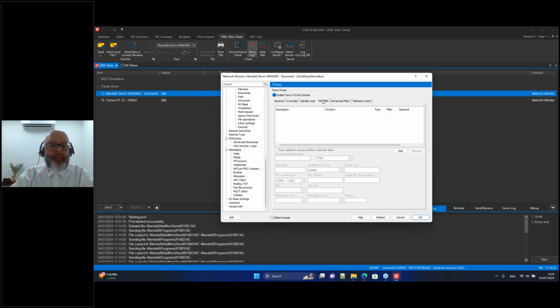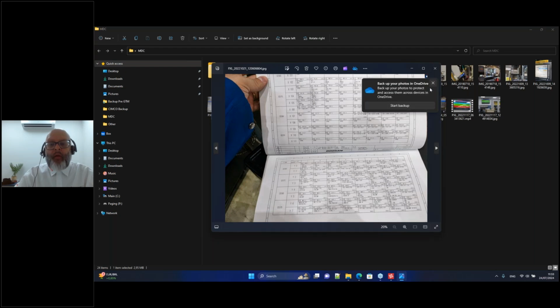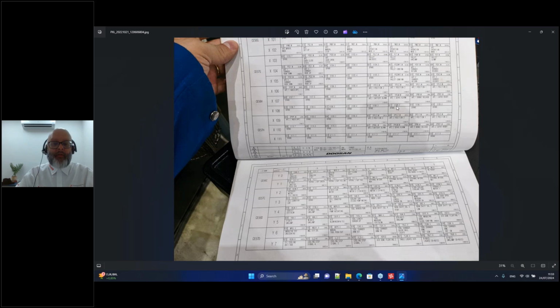So you monitor everything. But let's say you have an advanced thing that you cannot capture using the default option. So we read the PLC, and that's the advantage over analog signals, because when you have analog signals, you have to make a choice. You have to say, I'm going to get 4 or 8 outputs from the CNC, and that's it. You cannot add more. But if you are reading the PLC, and this is why Ethernet-based solutions are better.